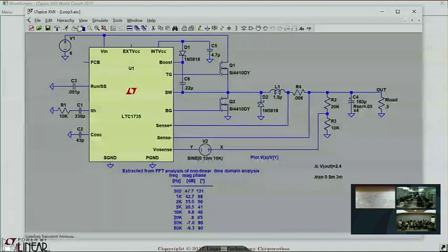Because I skipped some things when I went around the feedback loop. First of all, this capacitor will have ESR, that is a zero. And see this capacitor? We buy that capacitor, that resistor, that is another zero. The transfer function is actually two poles and two zeros, which means that it is not remotely close to oscillating. But what about that delay? The delay could mess up any feedback loop.